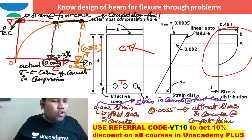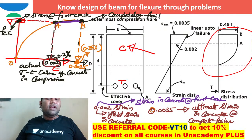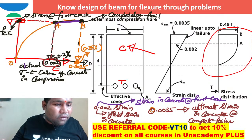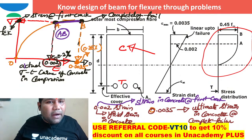So from A to B, instead of going in a curved fashion in this way, in the idealized stress strain curve we consider it differently. This is the actual stress strain curve. How can I consider the revised stress strain curve, right? And what is this zone? AB zone is nothing but the crack widening zone. Can I write that one?